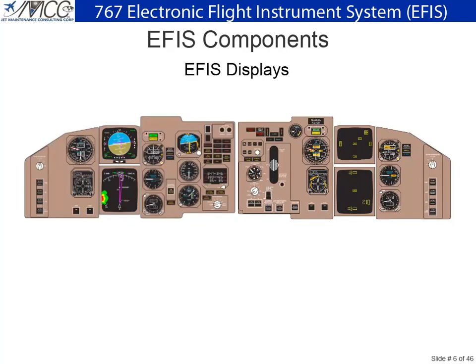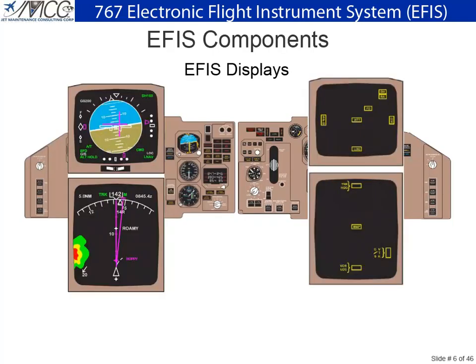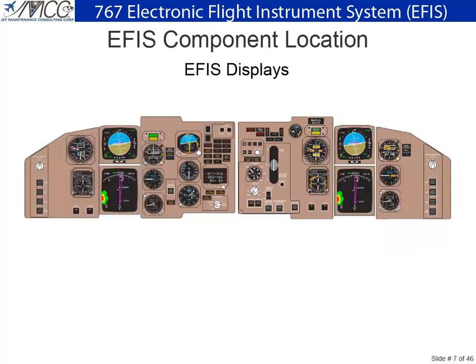The displays associated with the EFIS are the EADIs and the EHSIs. The displays are color CRTs, or cathode ray tubes, which receive symbol data from the symbol generators. Each set operates independently under normal conditions and has a dedicated control panel, remote light sensor, and symbol generator. The indicators are also capable of displaying text information such as flight parameters and system status. The EFIS displays are located on the forward instrument panels.